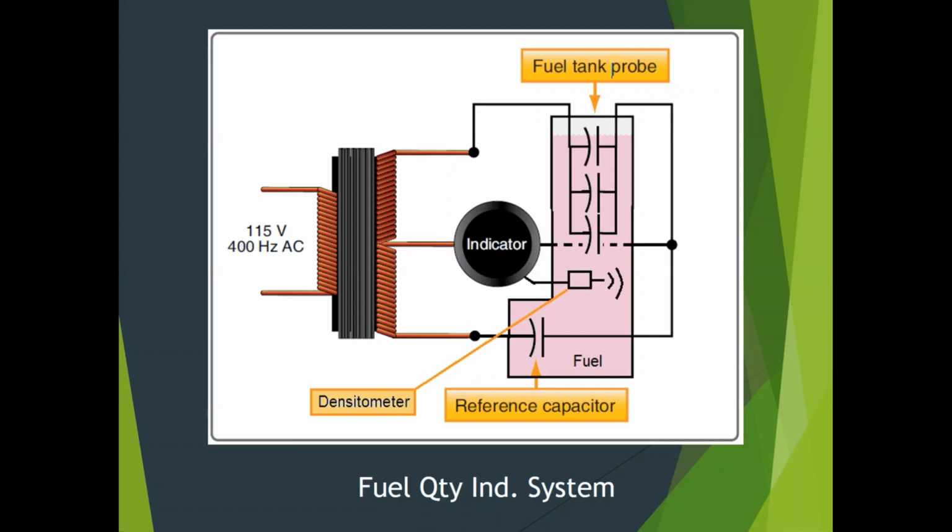Remember I talked about the compensator wash line when we were fueling? That's directed at this reference capacitor, this compensator. Reference capacitor and compensator are the same thing. These ones, fuel washes off of them, fuel gets on them, fuel washes off of them, fuel gets on them. So it's constantly washing the level sending capacitor. It's cleaning those plates as the fuel goes up and down. But this reference capacitor, this compensator, oftentimes will never